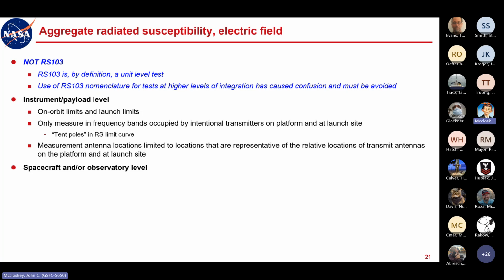And I'll point out that with RE testing, the scans are generally pretty quick, even with the old frequency swept receivers. If you've got a narrow, well-defined receiver notch, those sweeps are generally pretty quick. So you're in a little better position with radiated emissions if you're in any doubt about an antenna position. Do you need 4? Do you need 5? It's not going to make that much of a difference in time if you just go to 5, right?